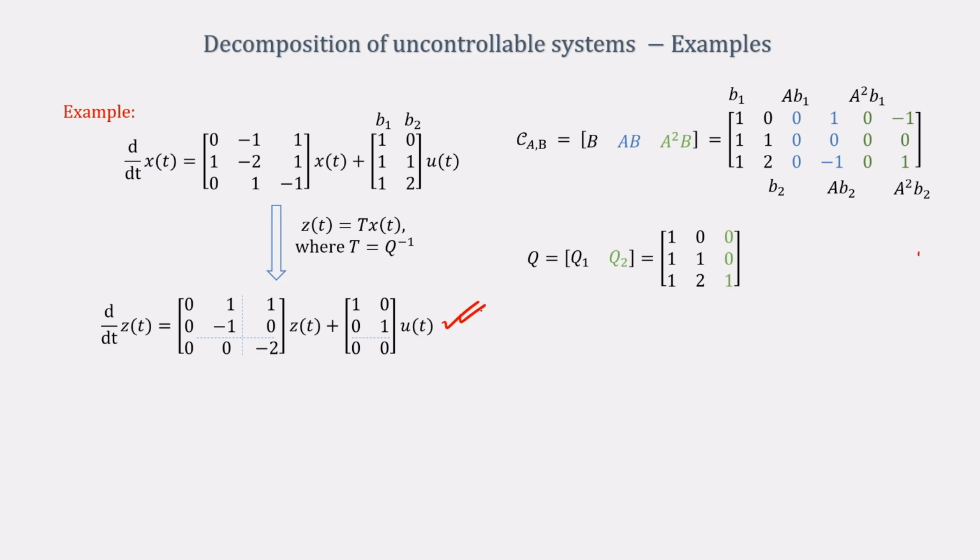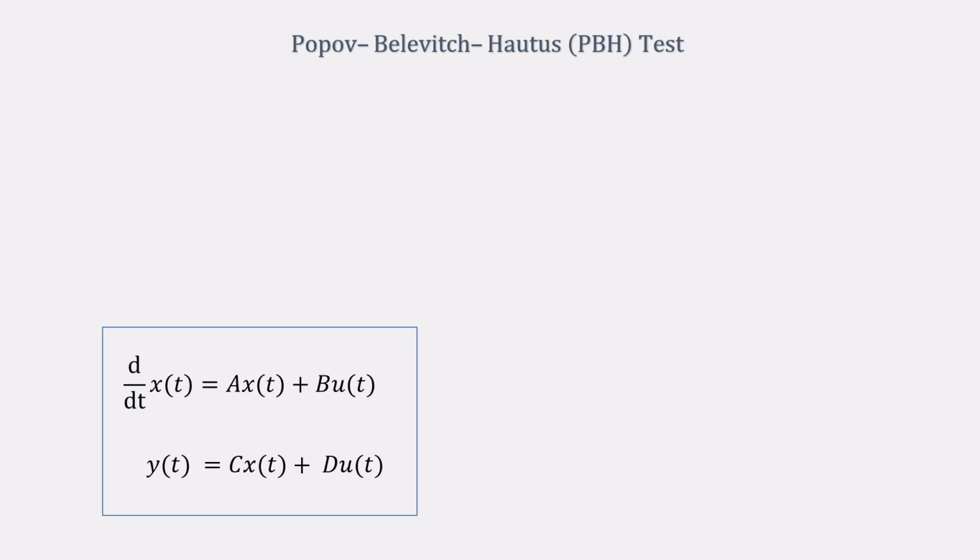Notice that we have decomposed the system into 2 parts in some way, and we will see that using this decomposition we can come up with a state feedback controller that changes the eigenvalues of the actual system. Now, this block upper triangular form also gives us some more information about the system, and this brings us to what is known as the PBH test.